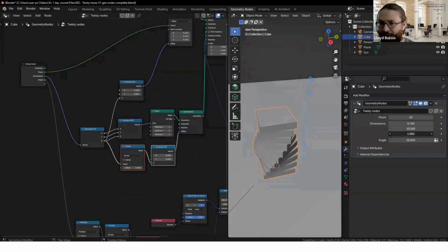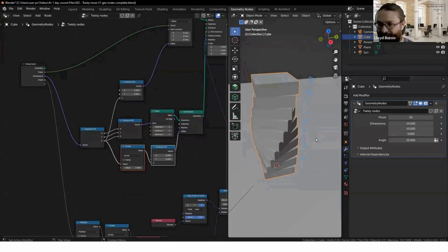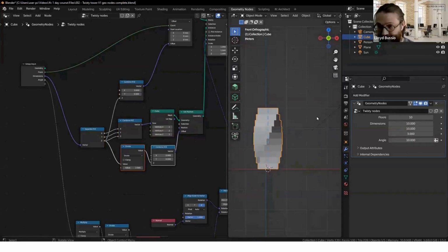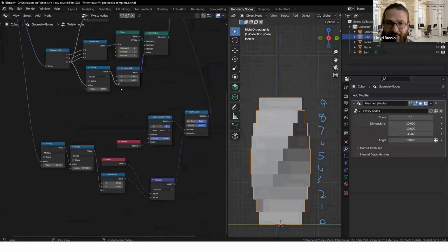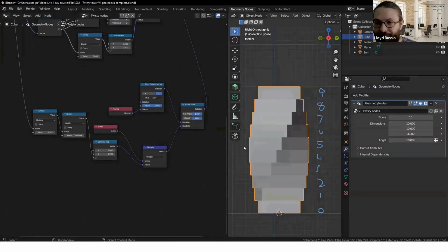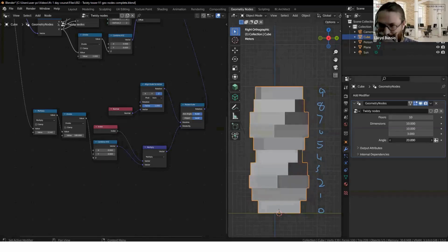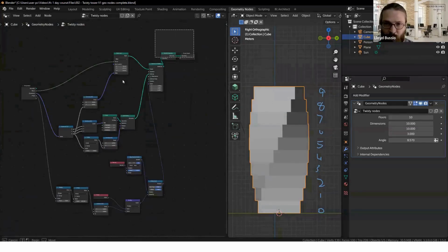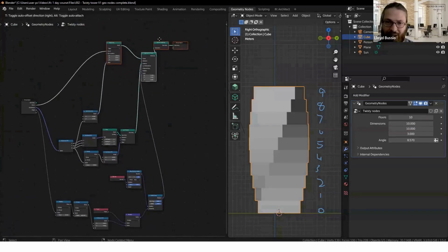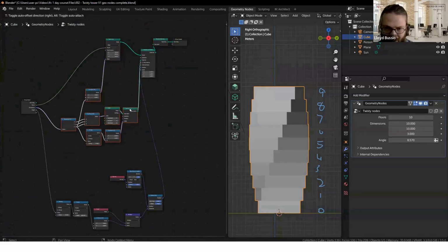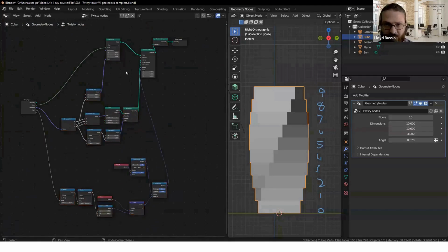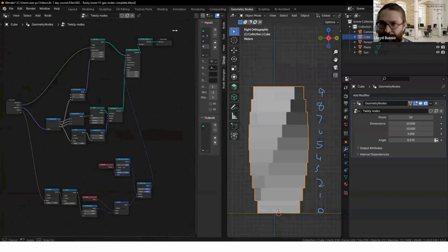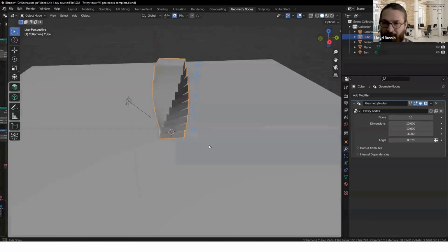And we can make it taller and shorter. And I'm just going to stick to my base values here. I'm going to go back to our elevation view. And then this bottom element is just the rotation. Essentially, we're just creating an angle that we can rotate this tower on. So once this is set up, that's the height, this is the size, and that's the rotation. Once this is set up, you can forget about this. That can go away. And we can just look at the 3D model.